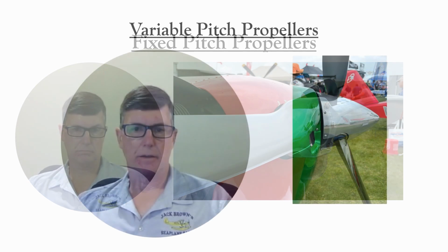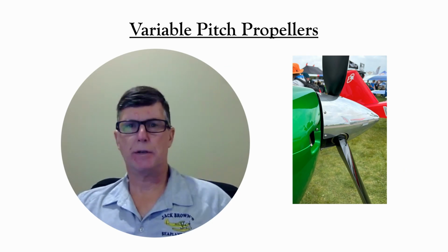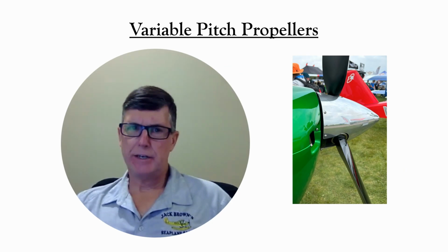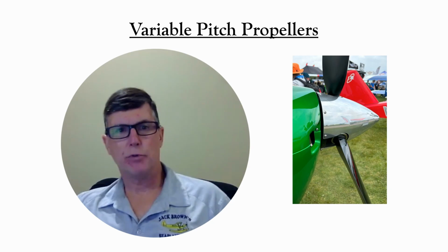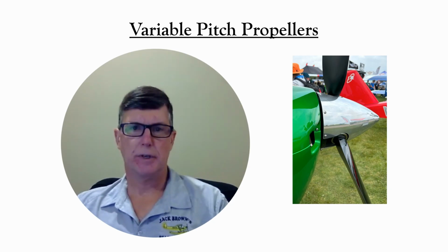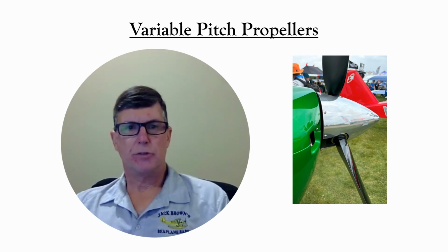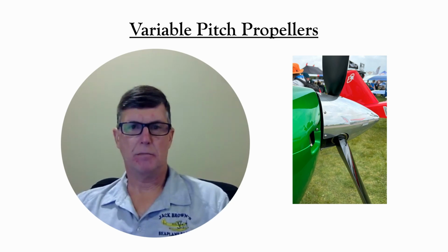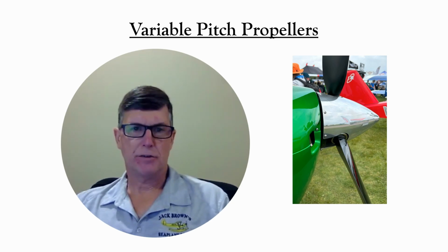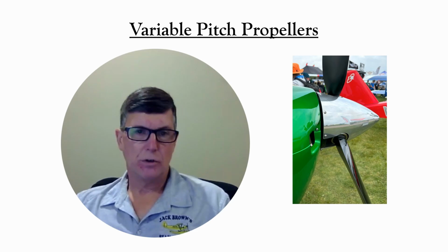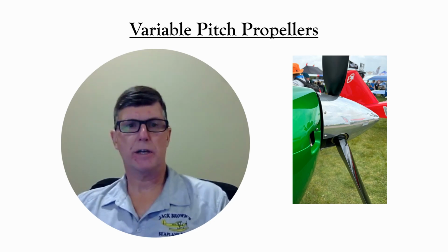A variable pitch propeller reduces the need to compromise between climb performance and cruise performance. The blades rotate with respect to the hub to make the pitch flatter for better low-speed thrust, or coarser for better high-speed efficiency.